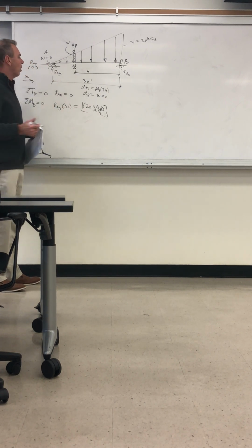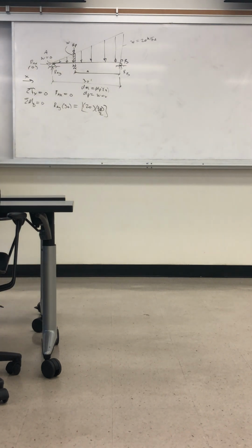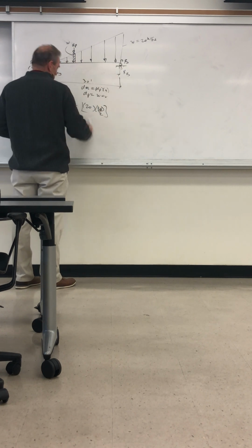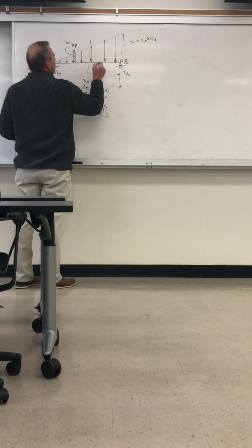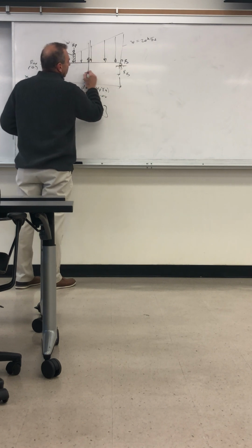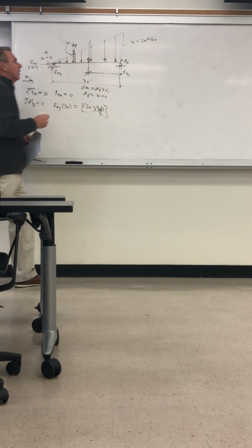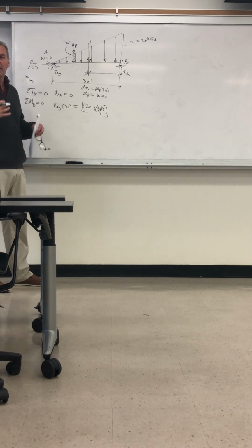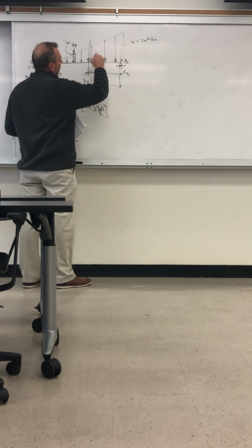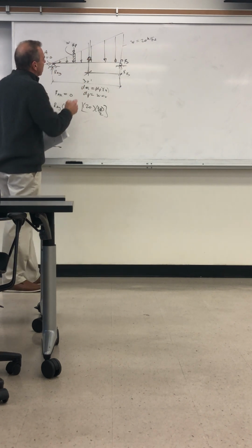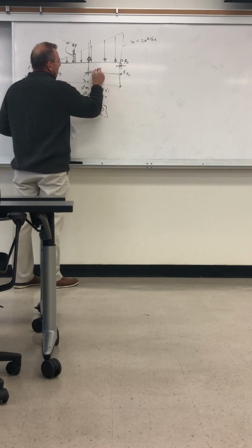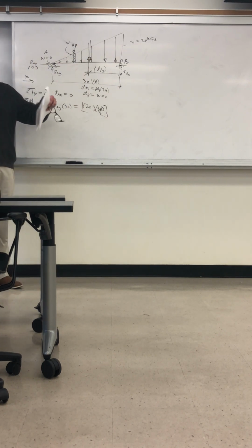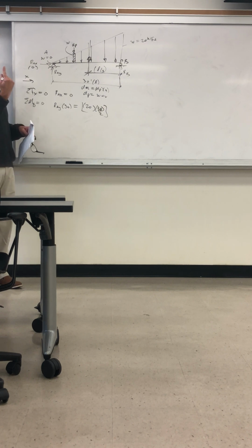And then we need to multiply that by a moment arm, and the moment arm for a triangular area is to the centroid. So it's 1/3 the distance. Here's our centroid location of the triangle, and we're just interested in the horizontal position of the centroid. We're going to be talking about centroids in this class, and deriving centroid equations for different shapes, even complicated shapes, using calculus. You can use calculus and derive this, but if this is 30, let's call this L, this is L over 3. If you cut this out of cardboard and turned it flat, that would be the point you would put your finger to balance it.